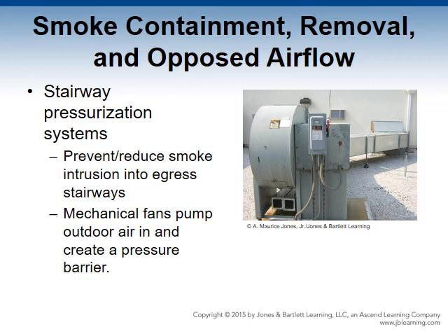There are several design considerations that can affect performance, such as the type of construction material used, the construction gap leakage, multiple doors opening simultaneously or being propped open, the number of stair levels, and the pressure difference should not make it so hard to open the doors. Requirements for stairway pressurization are included in the model building code and are common in high-rises.